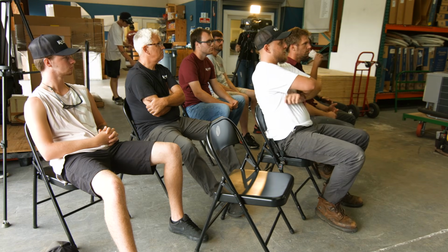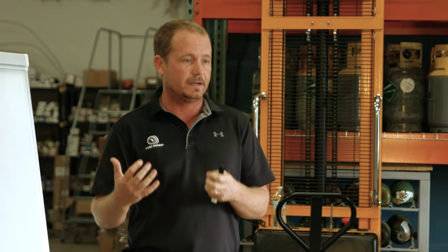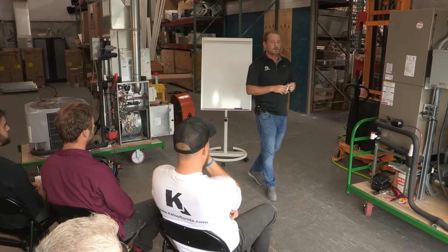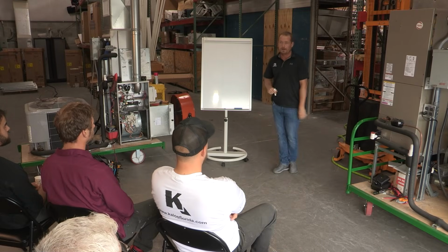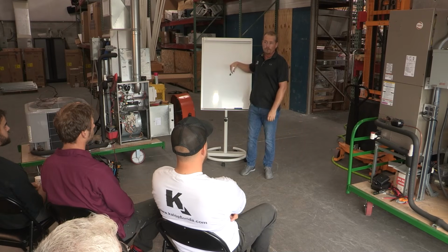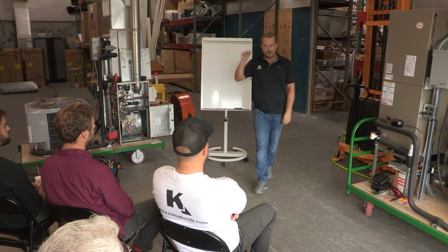It'll be a lot easier to teach you, exactly. It's going to be hard to teach if you don't have some of these basics memorized. And honestly, when I went to school, one of the best things my instructor, Ron Carey, did was he sent me to the whiteboard and said, all right, we're going to draw a compressor, condenser, metering device, evaporator, and you're going to do that over and over again. And you're going to mark them, you're going to mark the lines, you're going to write what's in each line and what each component does.